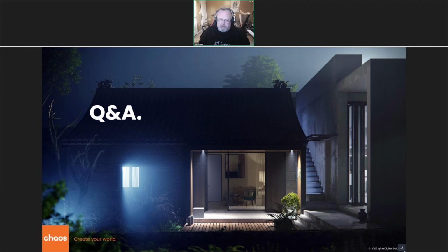Then people are asking, can I use distributed rendering? Obviously, if you have a shared drive, then yes, every machine will be able to access that and grab the assets. Even if you don't, with things like distributed network rendering, there's a checkbox to basically send the assets across from the master machine to the slaves. So you can do that if you don't want to be using a network drive setup. But with network drive setups, you should be able to achieve any end result you desire.